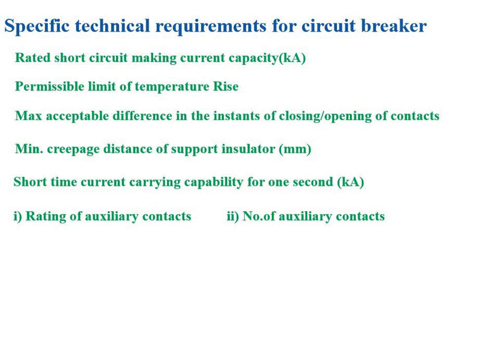And the number of auxiliary contacts: depending on how much interlocking you are going to do in your system, the number of auxiliary contacts is decided. Generally 10 NO contacts and 10 NC contacts are kept spare for the interlocking of the system for safety purposes. Then the breaking capacity of the auxiliary contacts you also have to decide.